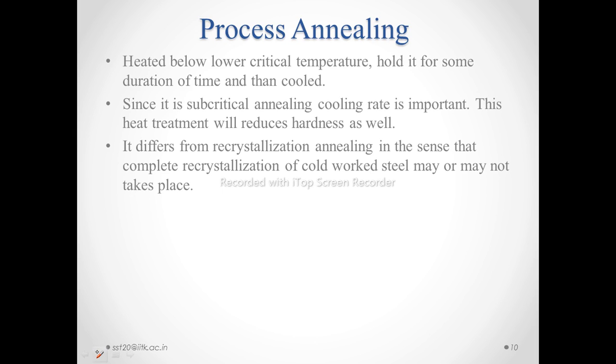Okay. The next annealing process is process annealing. In process annealing, we heat below the lower critical temperature, hold it for some time, and then cool at a slow rate. Since it's subcritical annealing, the cooling rate is very important in this process.